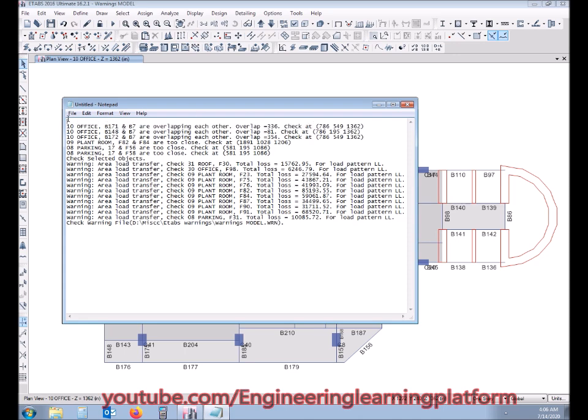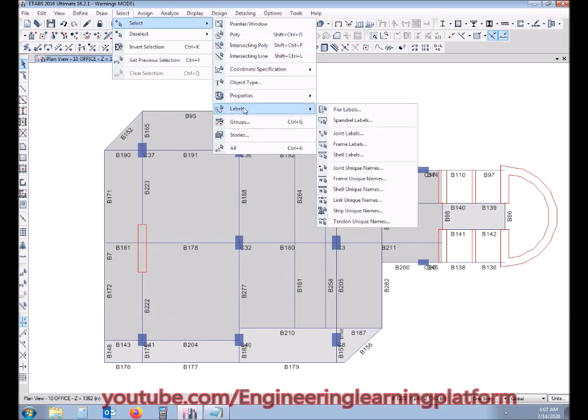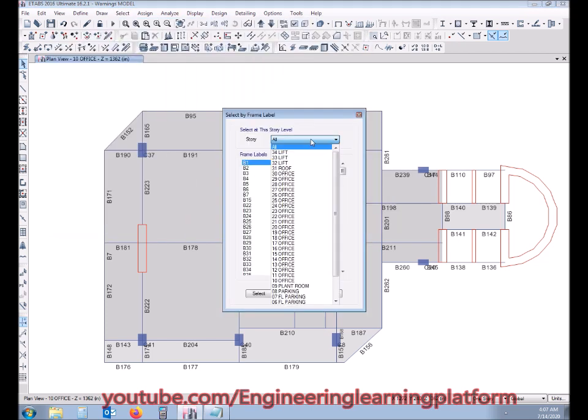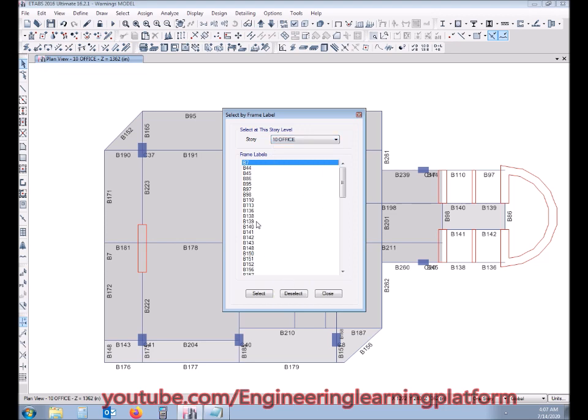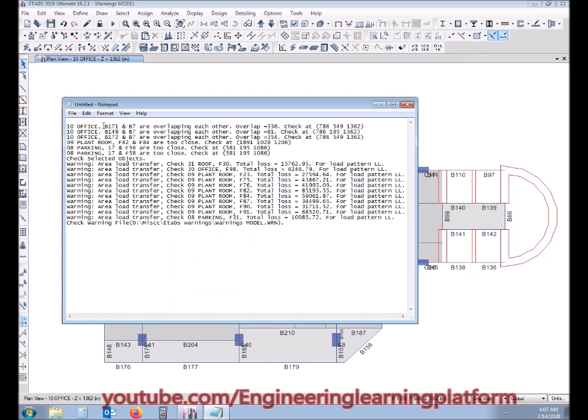Since 207 was the root cause of the error and the error was the same for the next level, we'll select the floor level to filter out and narrow the choices, and now here we'll select the beam ID we are actually looking for, which is overlapping.